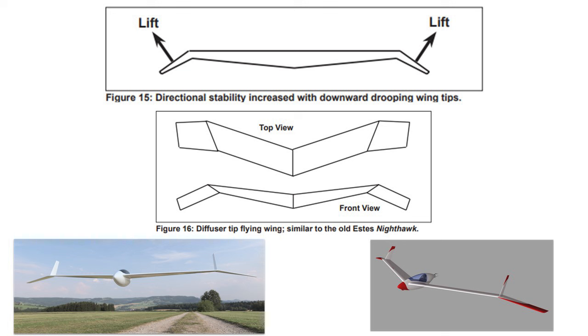Just remember that when considering diffuser tips, they do generate slight downward lift. Since these can replace fins and rudders and potentially some wing twist if designed correctly, then the lift deficiency caused by the diffuser tip can be tolerated. Alright, back to the traditional winglet geometry.